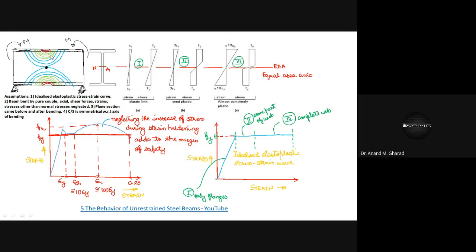The physical meaning of this is that these stresses are now in the plastic zone. They have entered into the plastic zone, and you can see condition 2, or loading condition part 2, can be correlated with this condition. That is, some part of the web is getting affected with this stress, both on the compression as well as the tension side. So what is the variation? It is something of this sort.